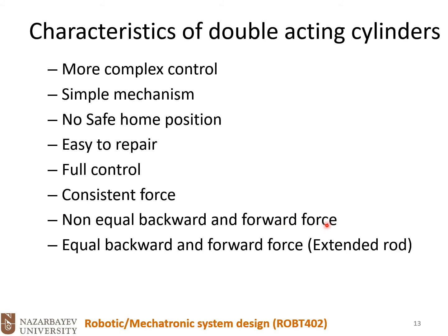Non-equal backward and forward force for the case of simple double acting cylinders, but the backward and forward force is equal for through rod double acting cylinders, and we should be aware of that. So, equal backward and forward force for the extended rod or through rod.